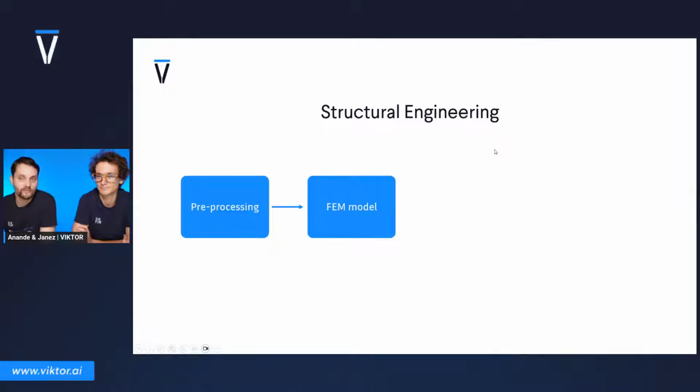And with that, you build some kind of finite element model, which could be ETABS, SAP or other software. And with that finite element model, you do your calculations. You often export results from that finite element model, and you put that in some kind of Excel sheet or Python script or whatever, and you do some post-processing. It could be just to do the unity checks, or to evaluate different load combinations, or to do some other more advanced post-processing, like calculating welds of connections, or rebars, that kind of stuff.